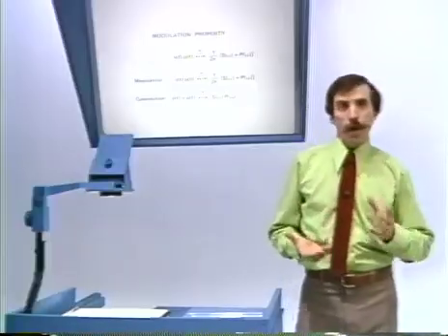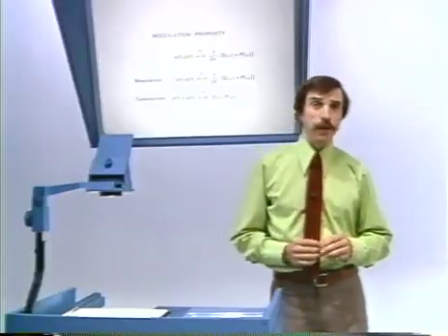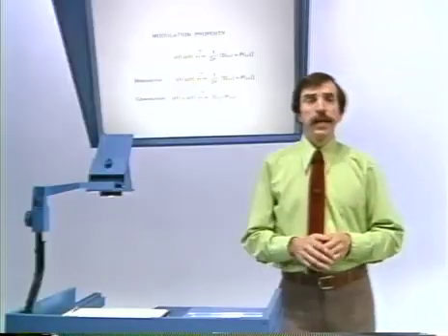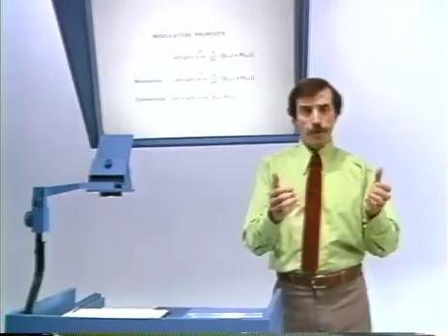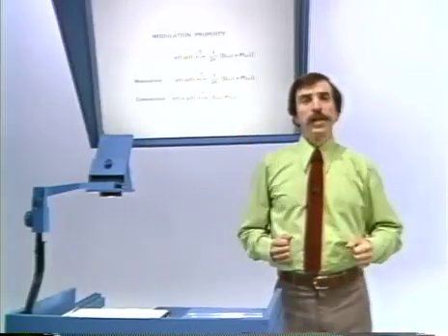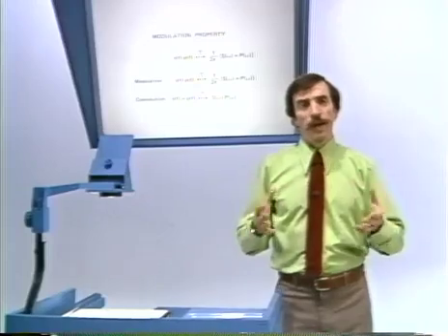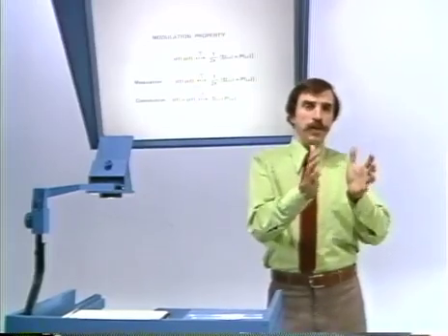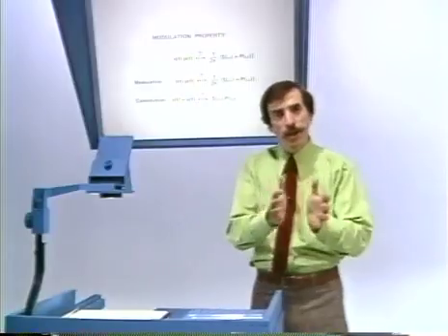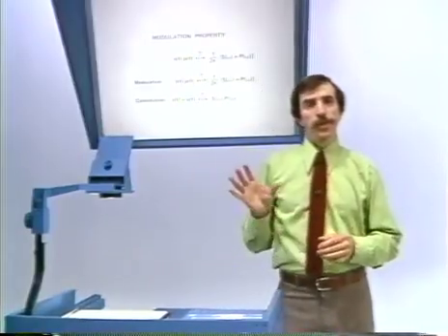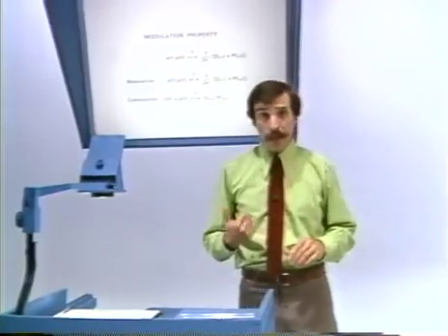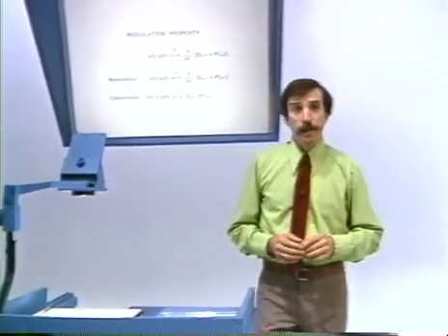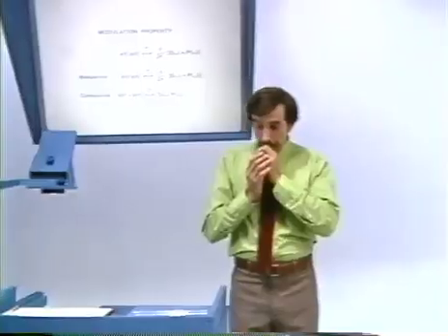And what the modulation property, as we'll see when we explore it in more detail, tells us is that if we have a signal with a certain spectrum and we multiply by a sinusoidal signal whose Fourier transform is a set of impulses, then in the frequency domain we convolve, and that corresponds to taking the original spectrum and translating it, shifting it in frequency up to the frequency of the carrier, namely the sinusoidal signal. And as I said, we'll come to that in much more detail in a number of lectures.